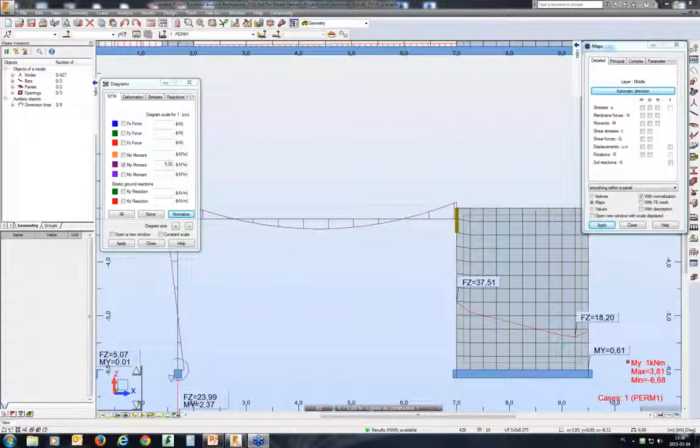When I have a slab with drop panels, what is the better option to mesh it? Okay, that's actually a question that has already been answered a couple of times on the Robot forum, but let me explain that again. The question is whether you consider any influence on in-plane forces for that.